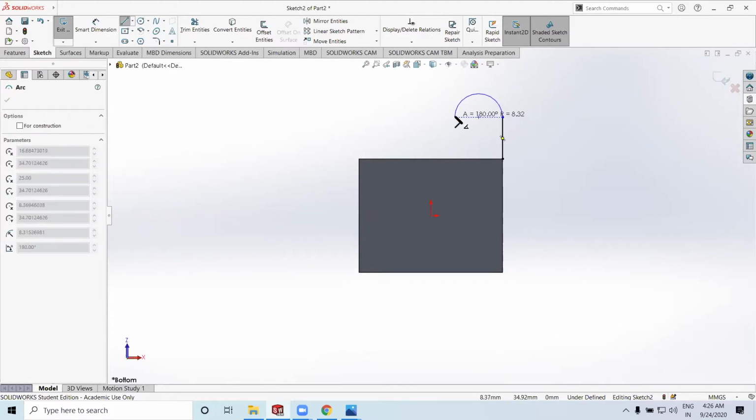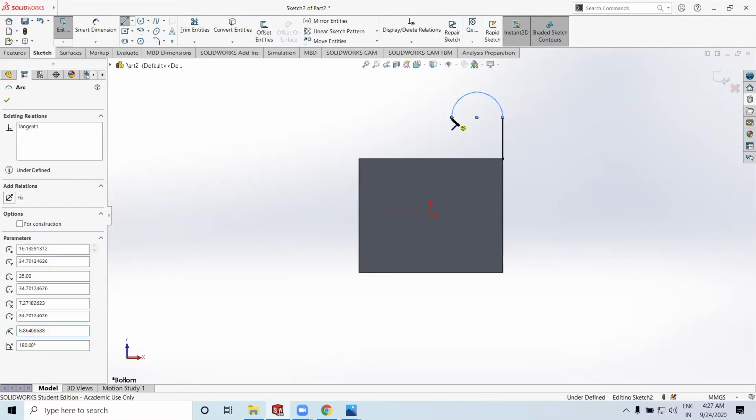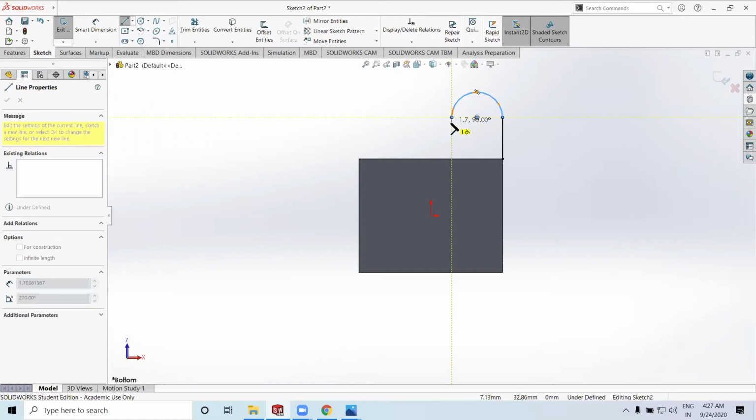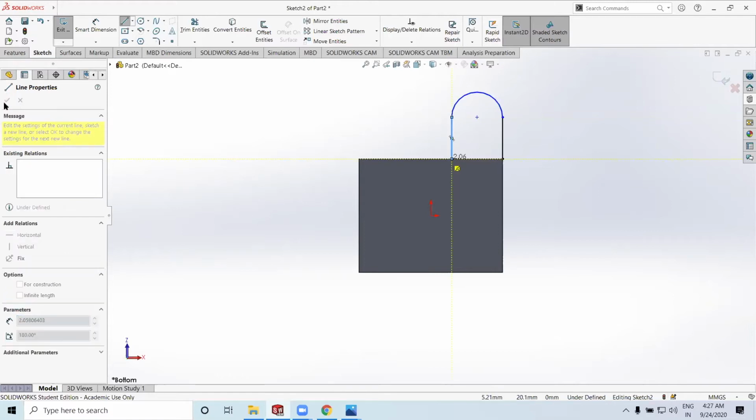You see this? When you hover around it, you'll see this dotted line which comes up, which is in line with this point. This can really help you. If you're going out of line, when you come back up and hover around it, you'll see this dotted horizontal line. So you click on it, and now you extend it back over here, and close this feature.